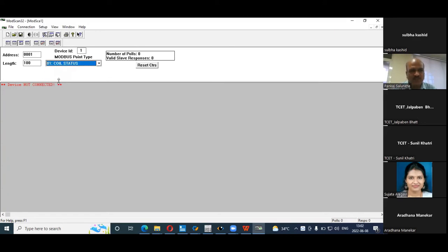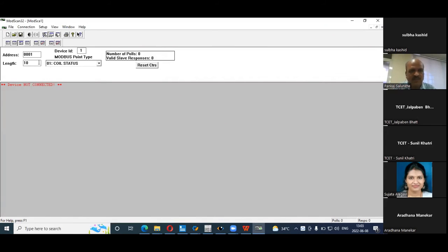So I will show you how you can read. Here you mention the device ID, which is the slave ID, the slave you read the data from. This is the starting address. Suppose I want to read the first 10 coil status, so I mention 1 to 10, length 10. So whenever I connect it,